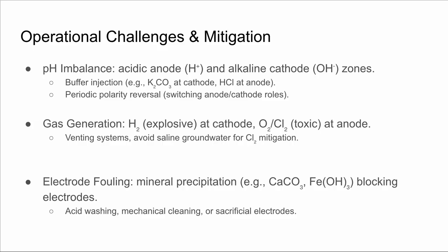Lastly, we have electrode fouling, where minerals like calcium carbonates can coat our electrodes and block our current. We can then clean them with acid washing, mechanical cleaning, or replace our sacrificial electrodes.